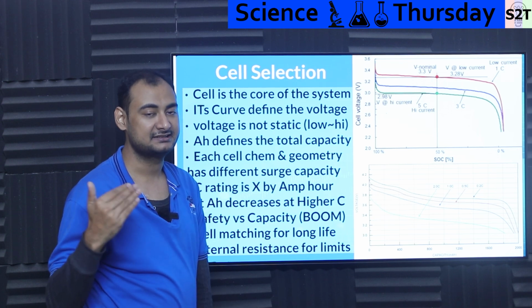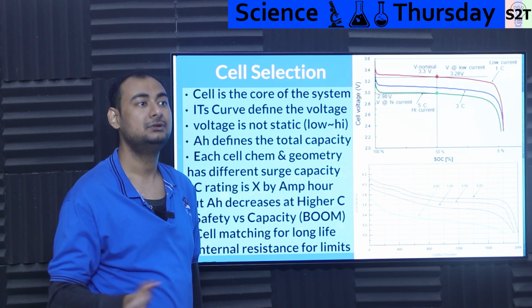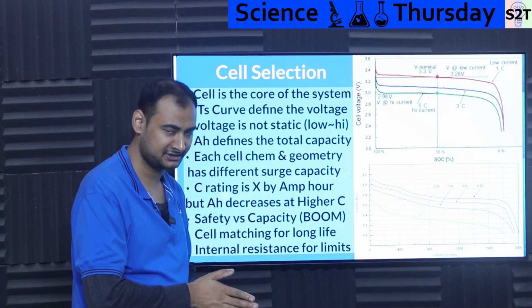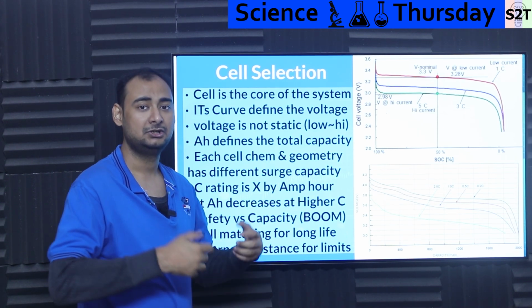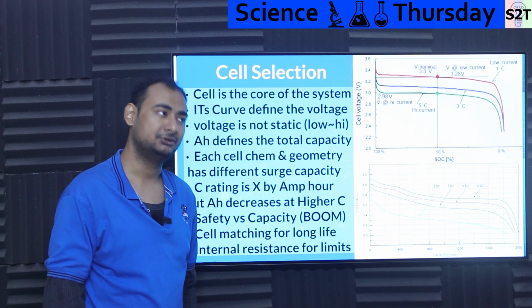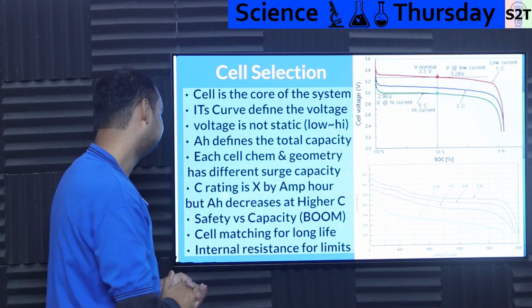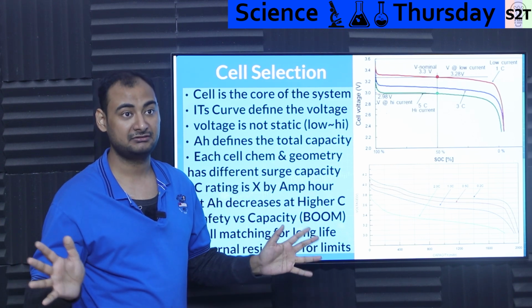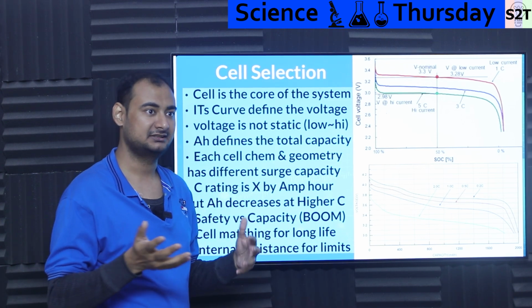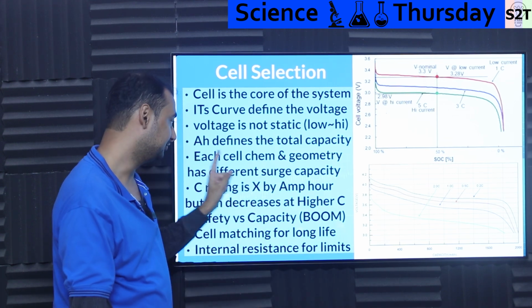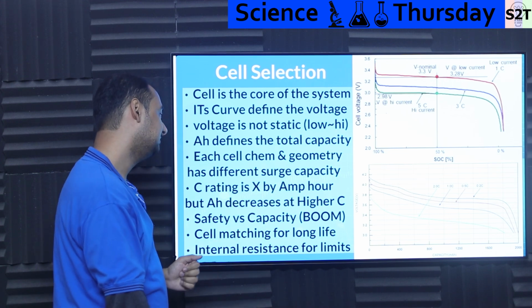Cylindrical cells fundamentally have a different geometry of charge flow and different internal resistance compared to prismatic. Prismatics generally have better internal resistance characteristics. So if you want something that can dump a very high surge current, you will generally focus not on cylindrical but prismatic designs. Again, internal geometry could be completely different. You may have a tabless design that Elon Musk was championing to solve that issue. You have to pay attention to that. Geometry and chemistry, all of them will play a role.